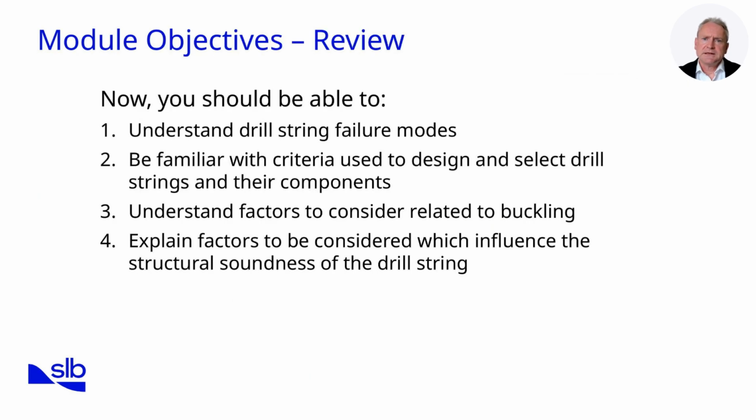In this session, we examined the key aspects of drill string design that influence performance and reliability. We began by looking at fatigue, focusing on how cyclic stresses develop and how fatigue design helps reduce the risk of failure. We then explored bending stresses in more detail, introducing concepts such as the section modulus, the bending strength ratio, and the stiffness ratio. These tools allow us to evaluate connections, which are often the weakest parts of the drill string.